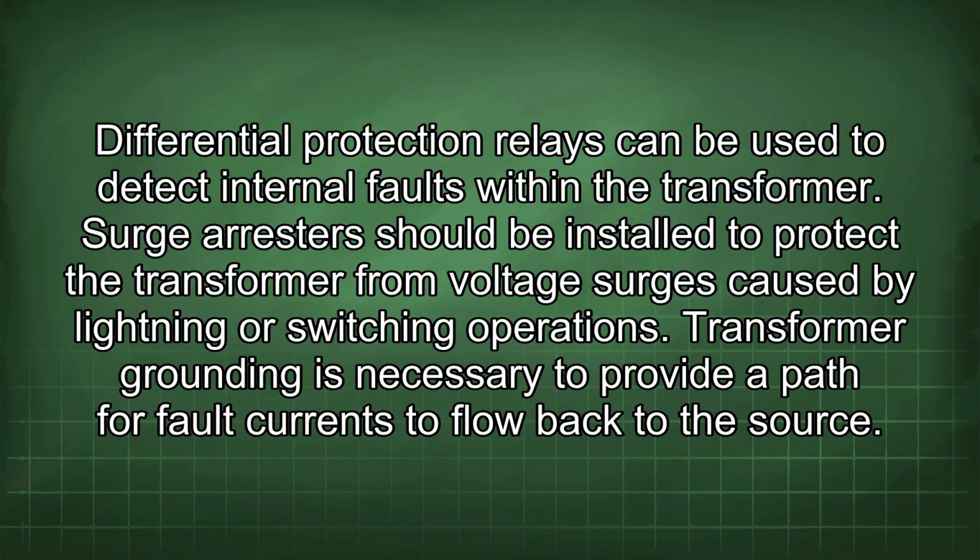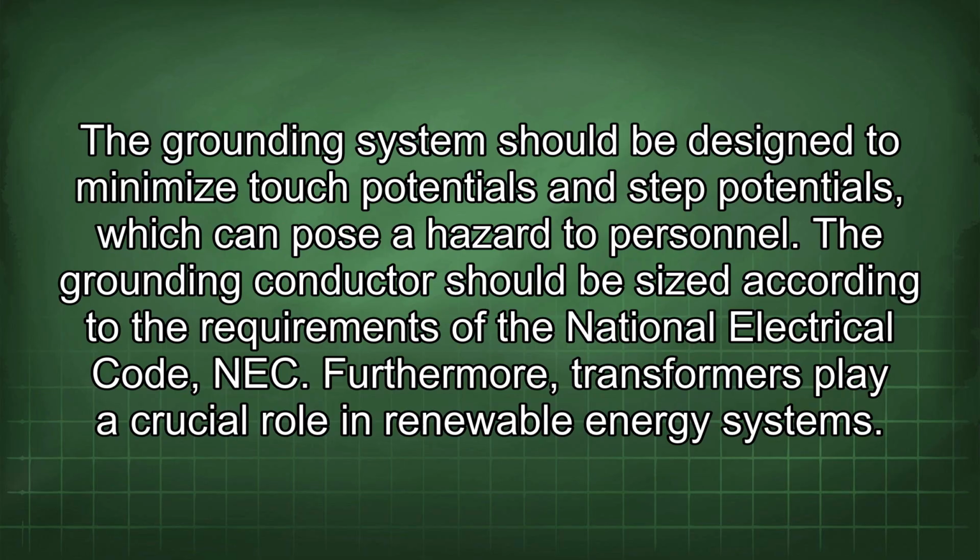Transformer grounding is necessary to provide a path for fault currents to flow back to the source. The grounding system should be designed to minimize touch potentials and step potentials, which can pose a hazard to personnel. The grounding conductor should be sized according to the requirements of the National Electrical Code (NEC).